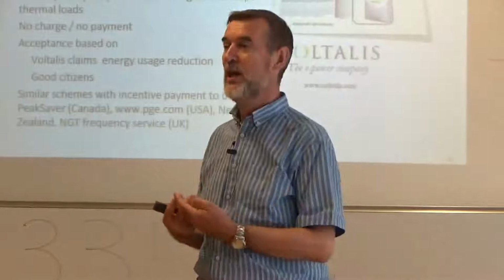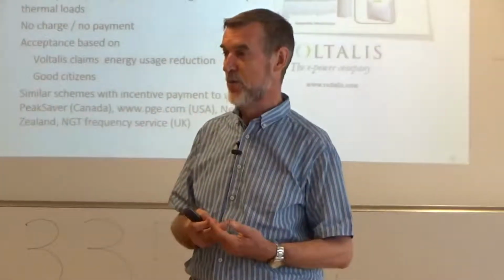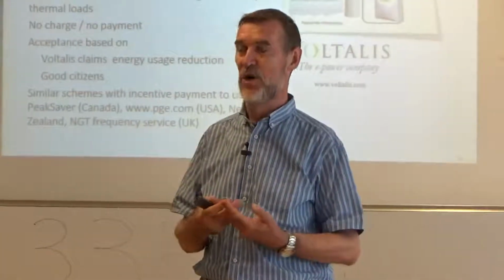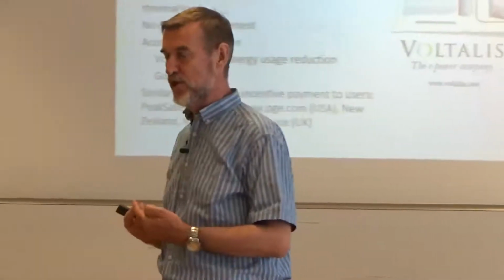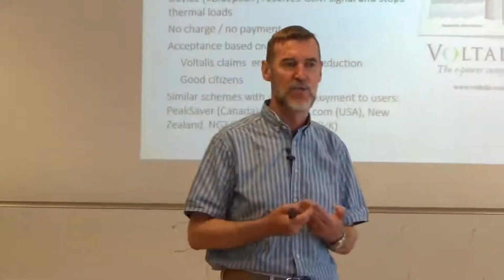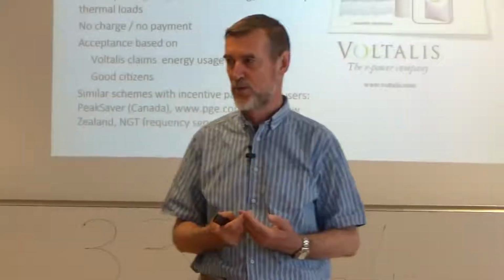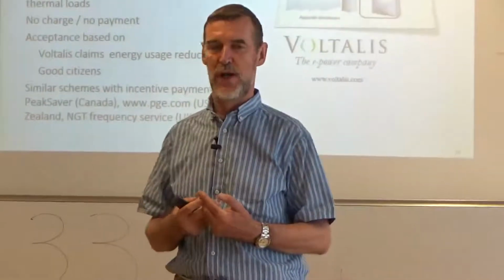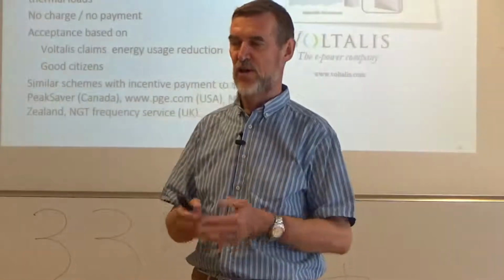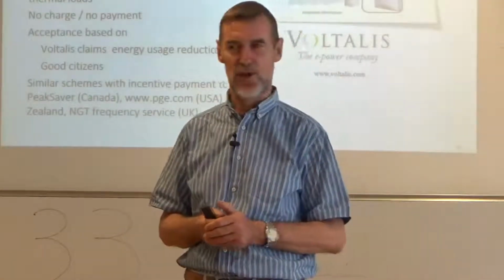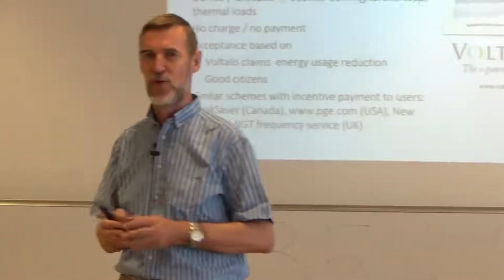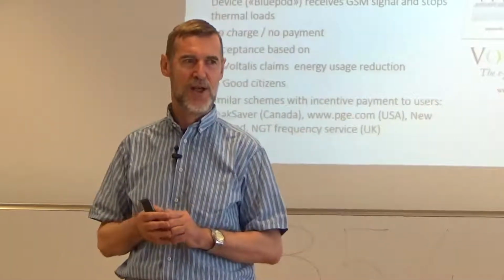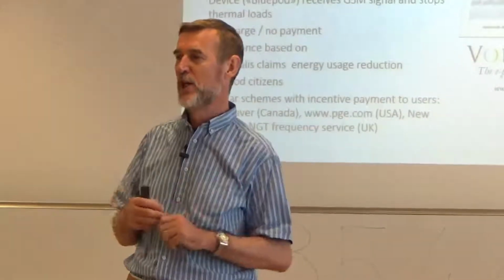So Voltalis plays in what is called the real-time market. The energy market, as you know, is done in several stages depending on the countries, typically day ahead and real-time. Real-time means 1 hour or 2 hours before execution. So when the European transmission network operators observe things and see, oh, this is a very cold winter day, we have a small problem, can someone produce 1 gigawatt more?